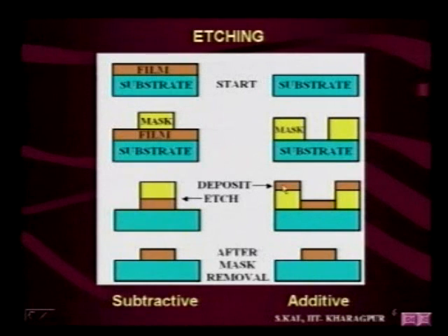Now, if the film thickness is more than the resist, the film will come up to this point, and it is very thick here. Look at the figure here. So if the film thickness, that means this saffron colored region, is higher than the resist film, then this gap and this gap are not available.